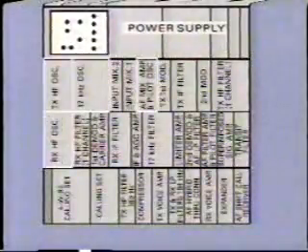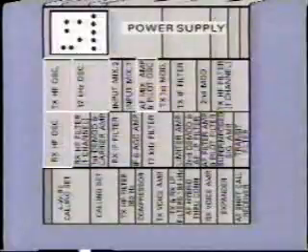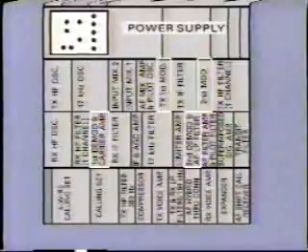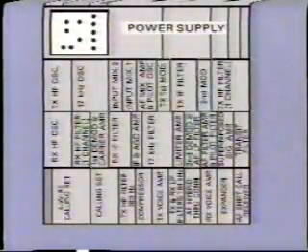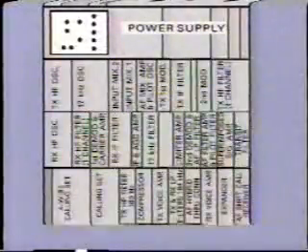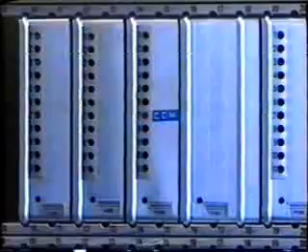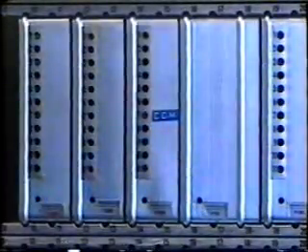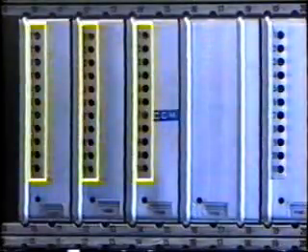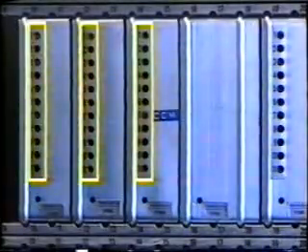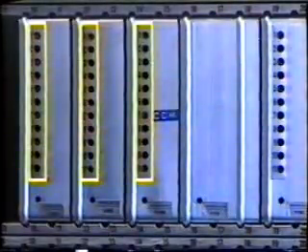This includes oscillators, which set the transmitter and receiver frequencies, modulators and demodulators to mix or demix voice and other audio signals, amplifiers, filters for outgoing and incoming signals. Maintenance of these units usually consists of test, identification, and replacement of defective components or modules. Voltage test points are accessible on the front panel, so that defective modules can easily be identified. Special test sets are often provided by the manufacturer.